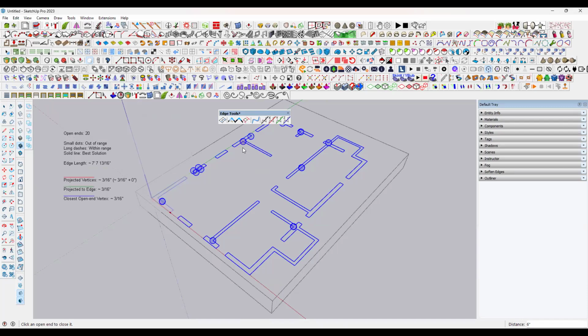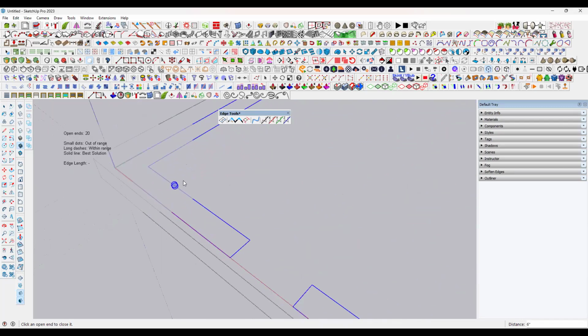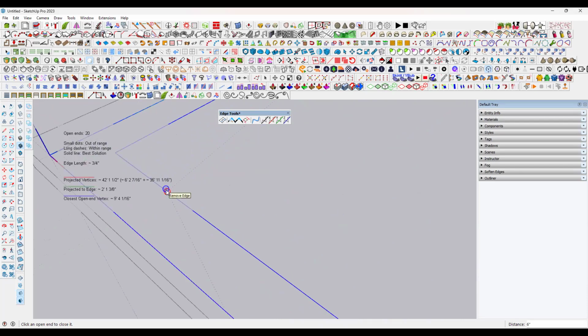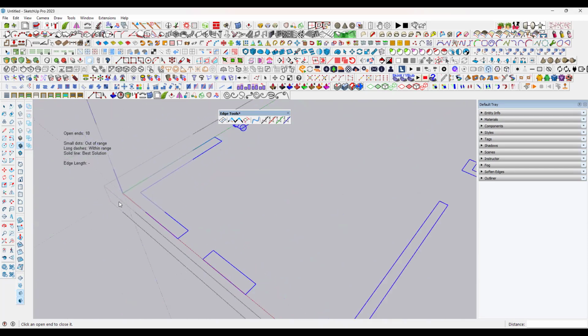See, we don't want to waste our time. It directly shows wherever you have mistakes, and we can go directly to that location, zoomed in. It tells us this is an open location and asks whether you want to remove the edge. I think there is some unwanted edge here, right? So I want that edge removed, and you don't have to remove it individually. I'll just click OK. See, whenever I click OK, that extra edge is automatically removed.